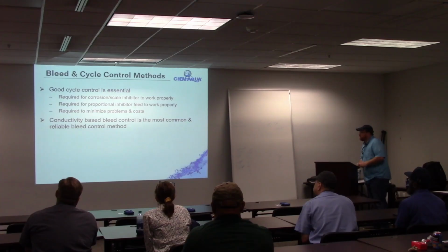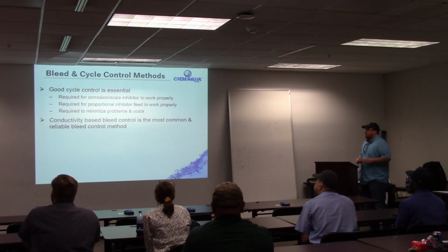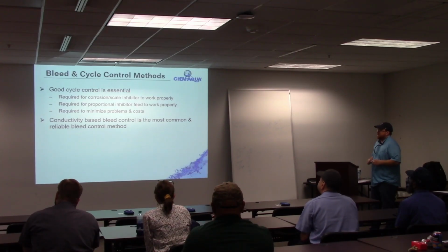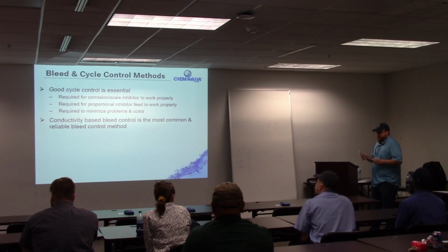Okay, so we kind of talked about this earlier, but the heart and soul of water treatment is controlling cycles, controlling conductivity set points, and then obviously making sure that you're feeding the right amount of inhibitor, feeding the right amount of biocide.